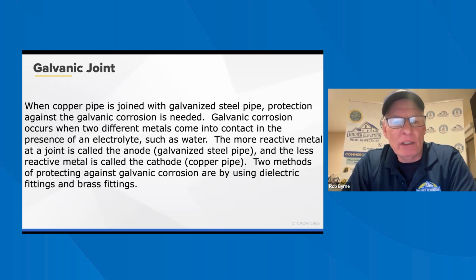Plumbing fixtures and appliances include fixture traps. Above ground drainage piping is what we're looking at now. Below grade drainage piping, that's underneath the slab, you won't see it. And below and above ground venting systems and piping to public sewers or private septic. So this is a drain line going out. You've got your clean out. Again, down here you have it. Those are important things to look at and make sure they're not leaking, and accessibility to be able to clean out that line. You need those.